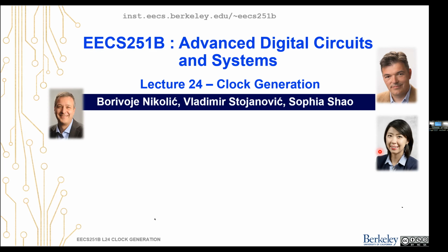So we're going to take a look today at how we generate that clock that's multiplied up as desired and then controlled, and what all the noise sources are that participate in this, and why that is important. Well, when you're doing PNR, you have to set your clock properties, right? So you have to say what jitter, what uncertainty you are expecting. Then the tool goes and budgets the rest in terms of inserting the clock buffers, etc.